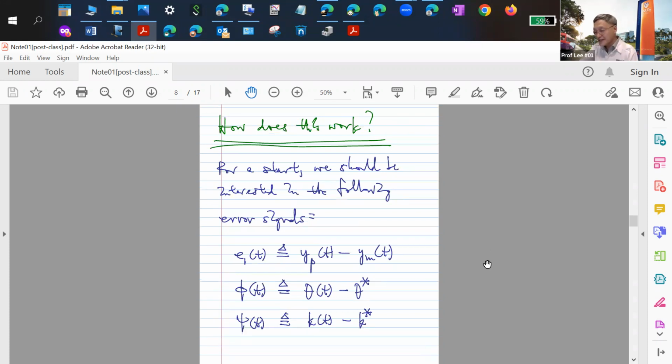Okay, so the way we saw from last week was to say, okay, let's look at the system now. In this way, we are doing adaptive control, and let's see what might be the signals that we are interested in. Clearly we'll be interested in the tracking error. We know that a perfect number theta star exists, even though we may not know what it is. We are putting in this control gain into our system. So this exists. We don't know what it is, never mind. This is what we're using. And clearly, theta minus theta star is the parameter error in this theta.